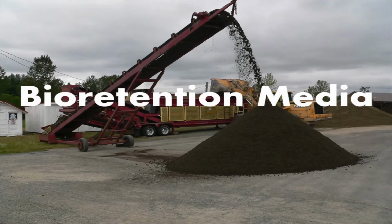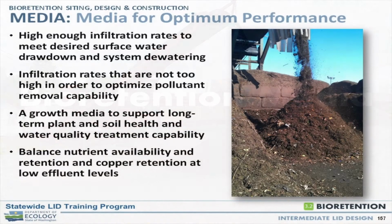We're going to talk about media, but from the perspective of media design. And this first slide is a list of the important things that bioretention media needs to do for us. First, one of the important things is high enough infiltration rates, surface water drawdown, and system dewatering. That's all part of your modeling procedure that you incorporate in your design.